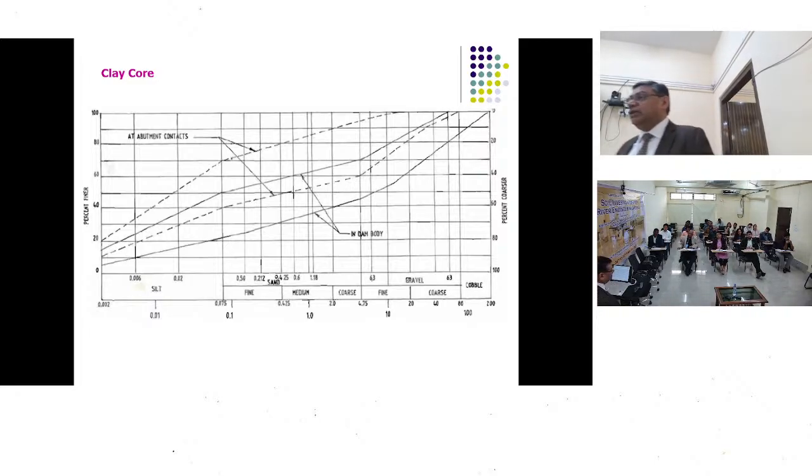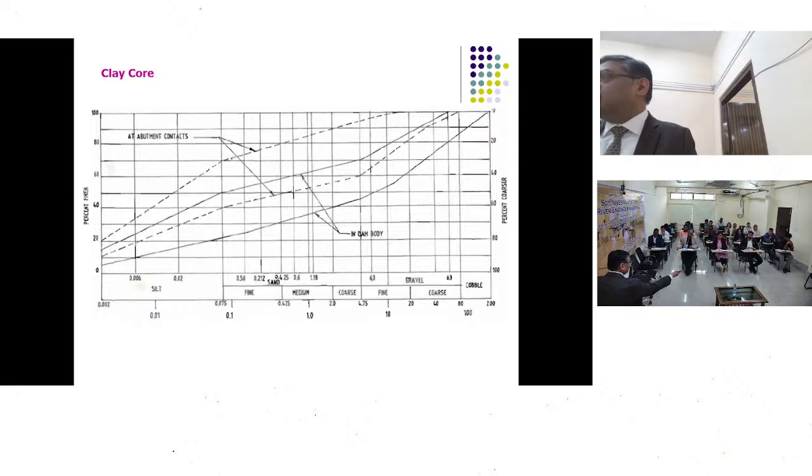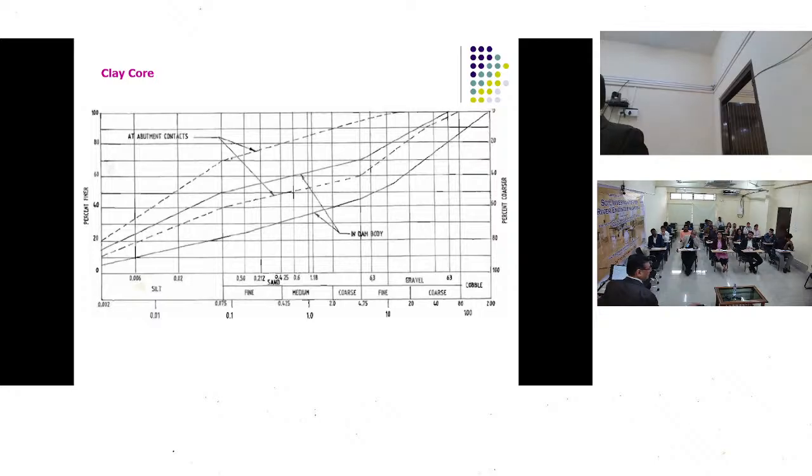And then you are going to work on the layers which are going to be placed. So all this planning is to be taken care of by the quality control persons. When I test the stockpiles and give the okay, the contractor will ask whether he has to use this stockpile or that one. I will say, okay, A, B and C are ready, you can take and use. The quantities can be used maybe in a period of 1.5 months. So you plan your testing for those, then you plan the testing parallelly for the layers.